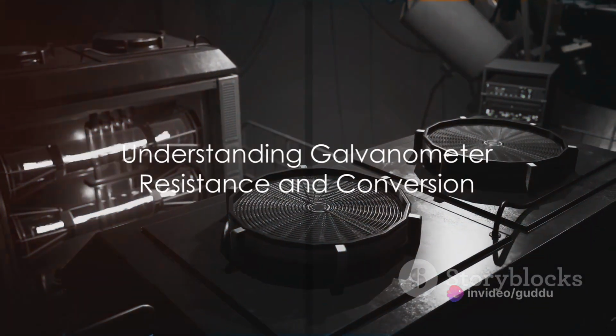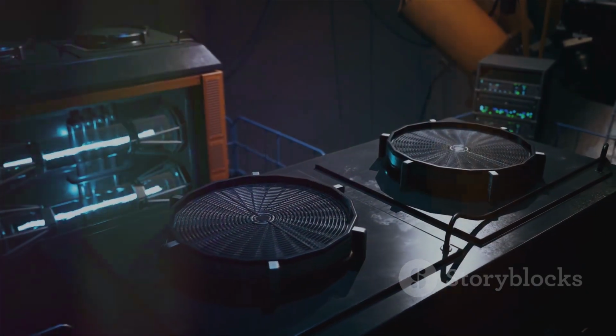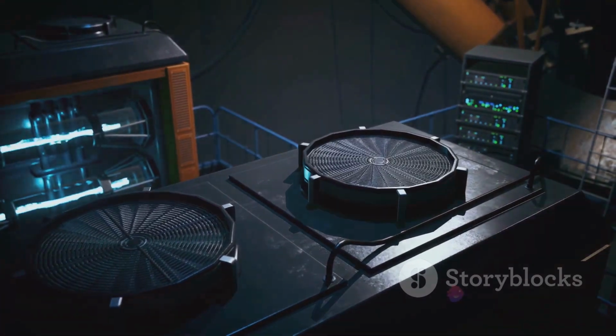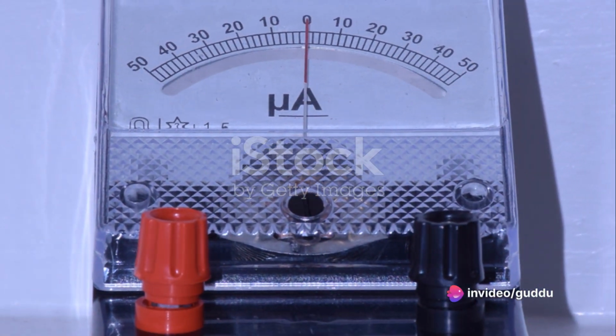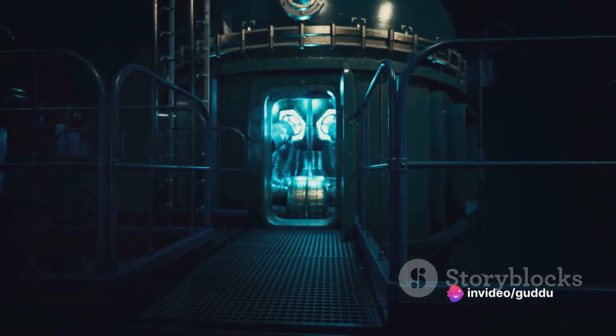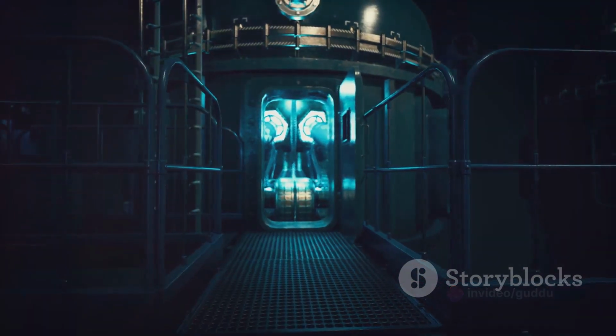Now, we'll determine the resistance of a galvanometer by the half deflection method and find its figure of merit. Connect a resistance in parallel to the galvanometer and adjust until the deflection is half of the previous value. The resistance of the galvanometer is equal to the added resistance.